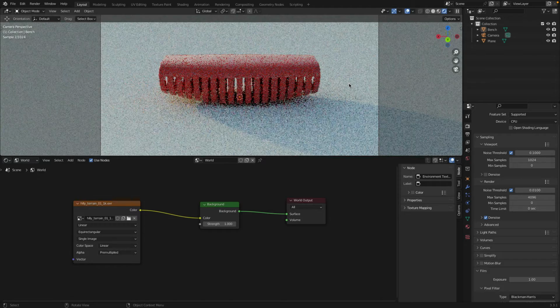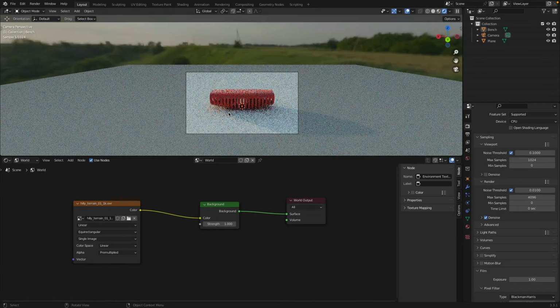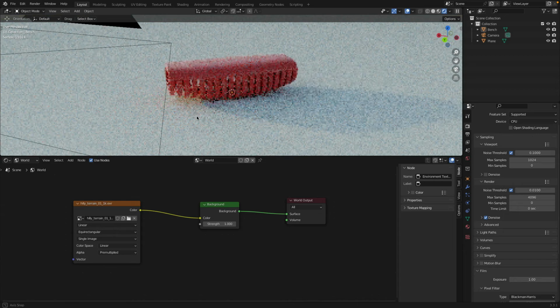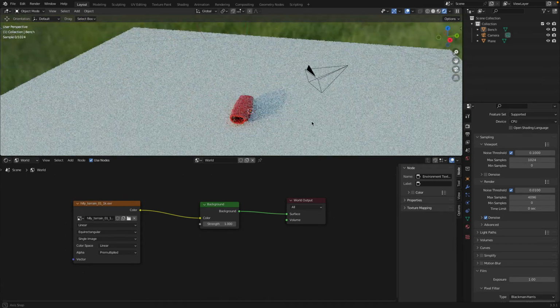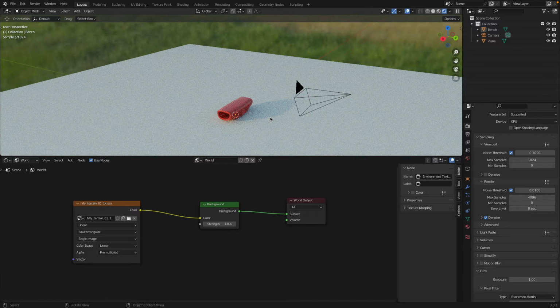And then when I turn on the rendering, look at this. You see, there is actually an environment. Beautiful. So the advantage of this rendering or lighting technique, image-based lighting, is the colors and the light. Everything is very natural. The downside is the limited ability to change it.